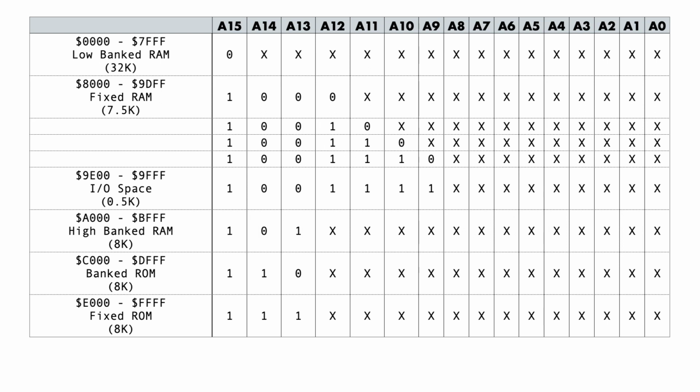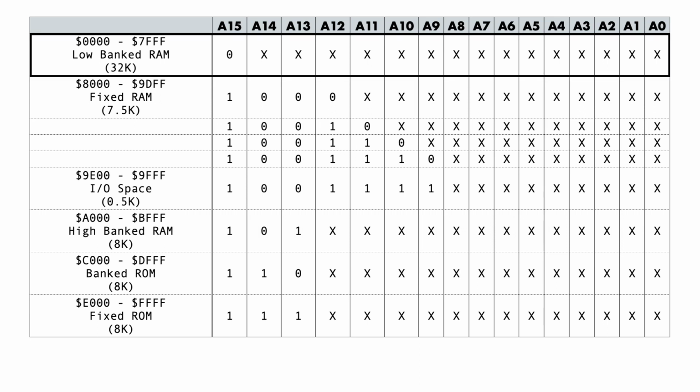And finally, decoding for I/O devices should be regular and minimize the amount of additional decoding logic that peripherals have to do themselves. And then also to allow for quite a lot of future expansion and experimentation. So based on those goals, I defined 6 basic regions. A low banked RAM region, where some amount of RAM, I haven't really decided exactly how much yet, can be banked in 32 kilobytes at a time.